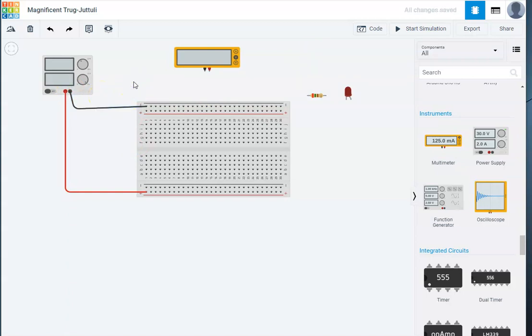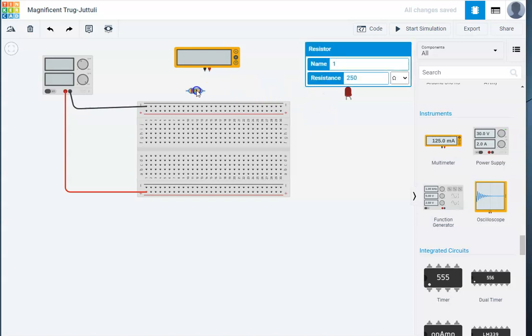Pretty cool. So what I'm going to do is I'm going to bring my positive to the positive strip here, and I've got the negative to this one on the opposite side. And I'm going to work across the breadboard just to make a loop. Remember, electricity's got to make a loop. All right. This little resistor, I'm going to rotate it. Resistors don't matter the direction they're in. Electricity can flow through them in either direction.